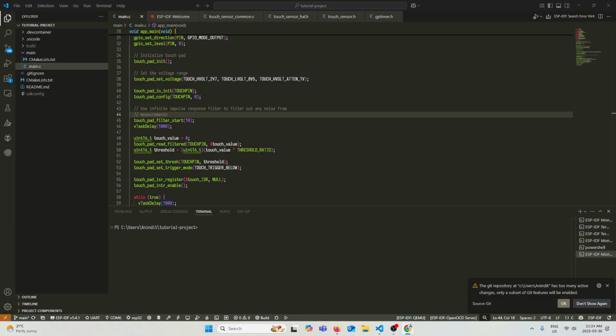Unlike the legacy ADC driver, ESP-IDF from version 5 and beyond has two modes. One-shot mode, where the ADC conversion only happens when you instruct it. If you want to get the output 5 times, you simply call it 5 times. Continuous mode, where ADC conversion is repeated automatically at a defined rate.